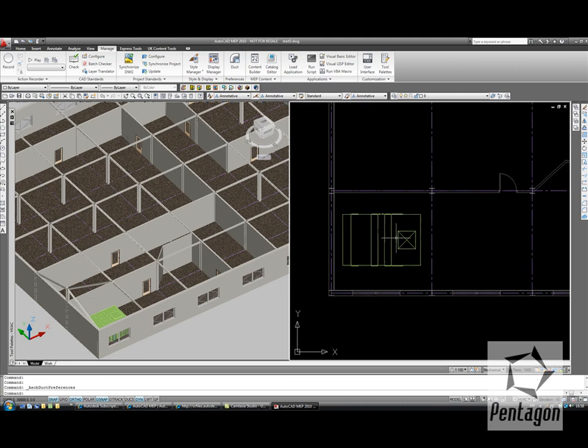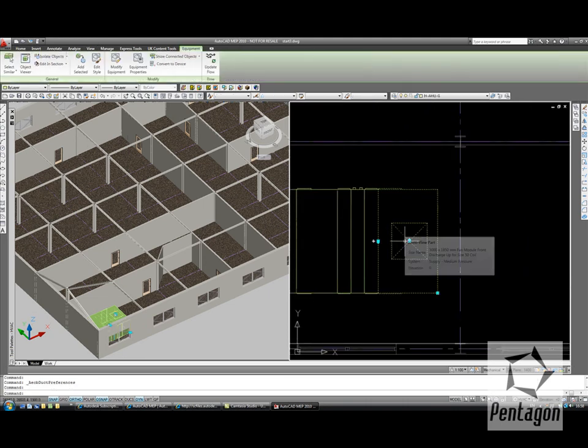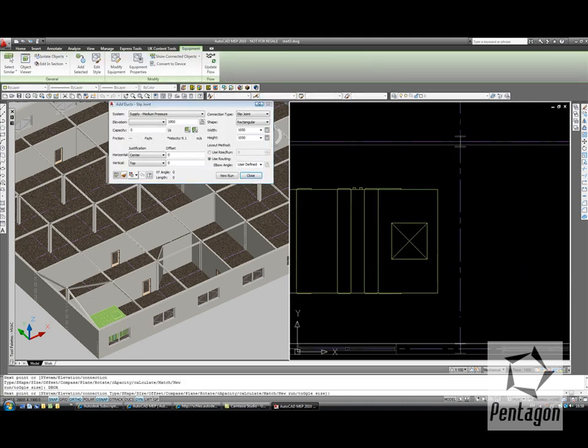So let's get started. I can pick my air handling unit and hit on the plus, and it'll immediately start to add in my supply medium pressure duct. It's detected that it's 1050 width by 1050 height. Because I've got predetermined elevations in there, I could say, well, let's swap it out immediately to a high level, and it adds my duct in.